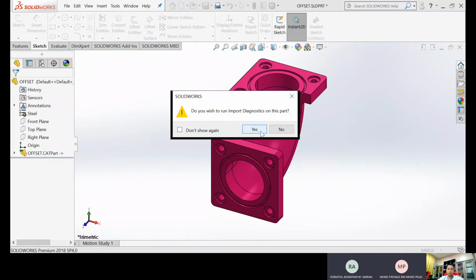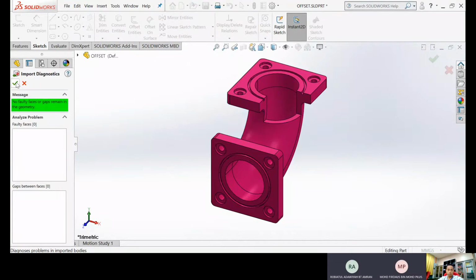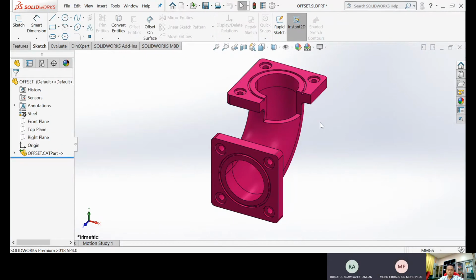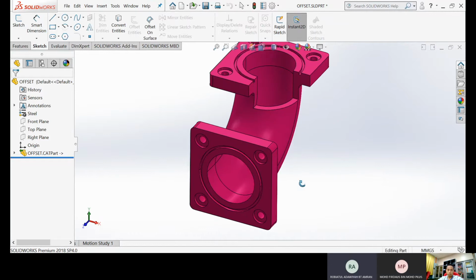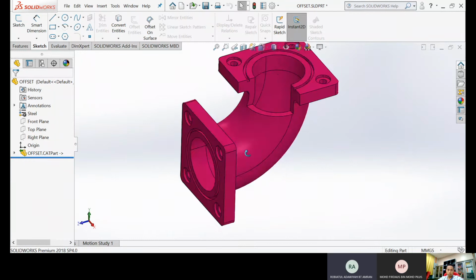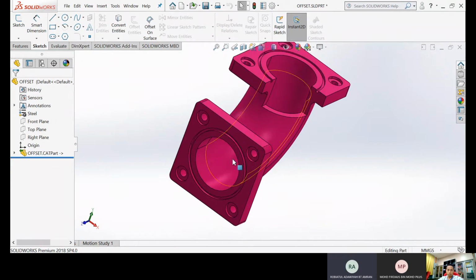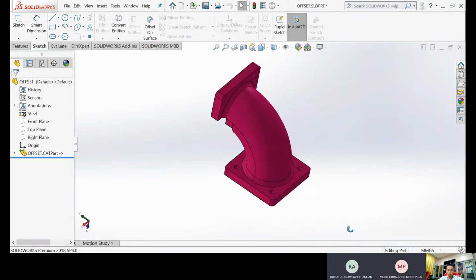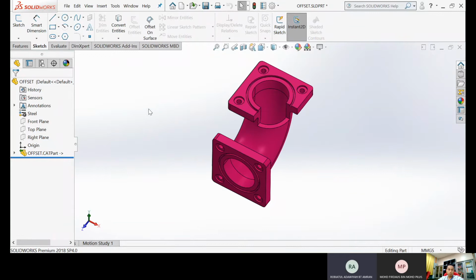The first step in reverse engineering a part is to capture the data from the existing part. Depending on the material and size of the part or facility, a variety of different scanning equipment can be utilized. The design process of the mechanical component involves 3D scanning and laser scanning that deals with creating a point cloud. The STL data can be used to manipulate and turn the feature into a surface that can be used. Step by step using tools given.